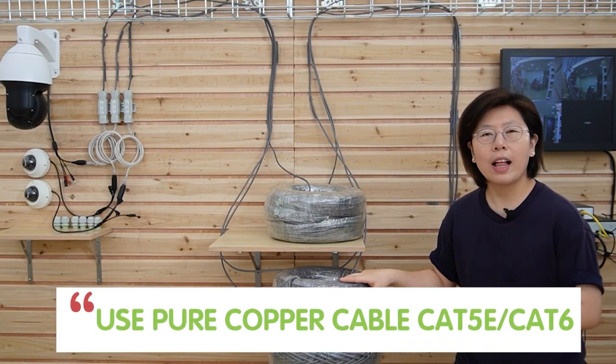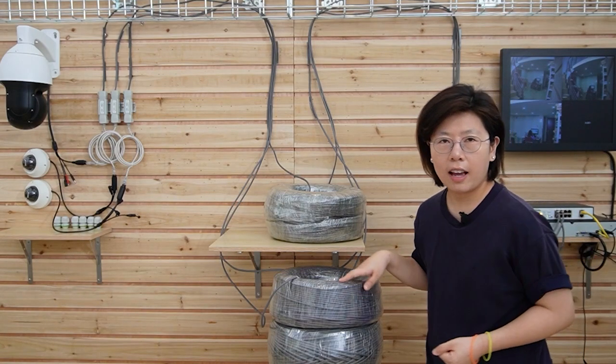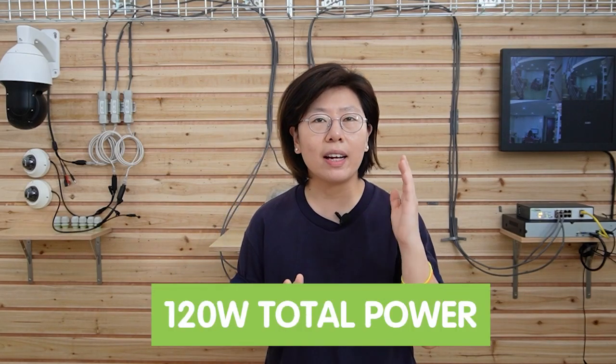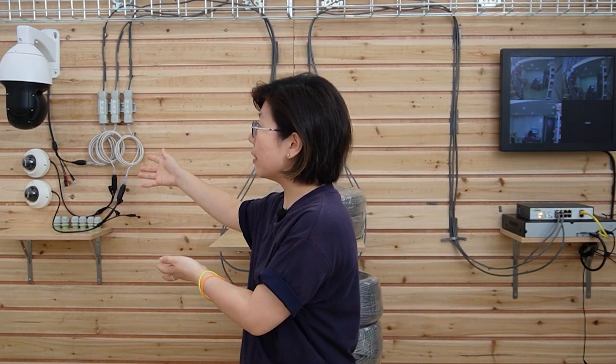Here are a few more tips for you. If you're doing a PoE connection, make sure you use a pure copper cable like Cat5e or Cat6, because copper has superior conductivity compared to other materials, so you can have stable power delivery. Then you have to be careful with the power budget. Our long-range PoE switch here has a total of 120 watts of power budget. If all the edge devices add up to over 120 watts, some of the devices may not work because they're not getting enough power.